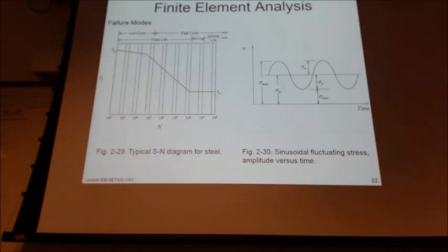We also have a fatigue failure mode, so we're trying to get below the endurance strength of the material. We have some sort of fluctuating stress that we're trying to cope with, and the 3 things that we have to make sure that we have a handle on are number of cycles, the loading history, and whatever safety factor we think we want to use for fatigue loading.